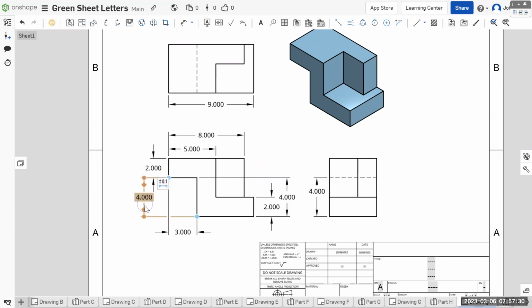So we can keep just this 2-inch dimension instead of these 4-inch dimensions because they're locating this edge or describing how long it is. Plus, if you're just thinking about how you'd build this, showing that this is 2 inches tall is super useful. And same thing over here. And yeah, we'll straighten things out at the end. And then the only other height dimension is total height.